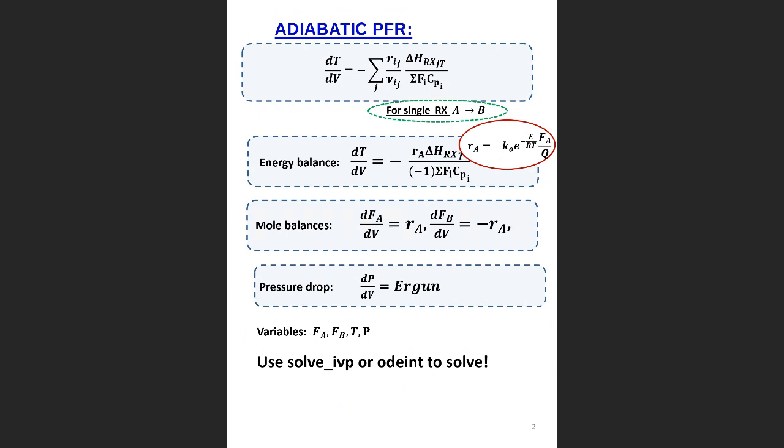You have many more variables than the few that I've just shown here. You have lots. This is just the variables for which I return differential equations. For the rest of the variables, I still need equations. My degrees of freedom must still be equal to 0. Okay, sorry, I'm talking to the crowd and not on screen. My degrees of freedom must still be equal to 0. And I must therefore match the number of differential equations and algebraic equations with the number of true variables that I have. So sorry if this confused you.